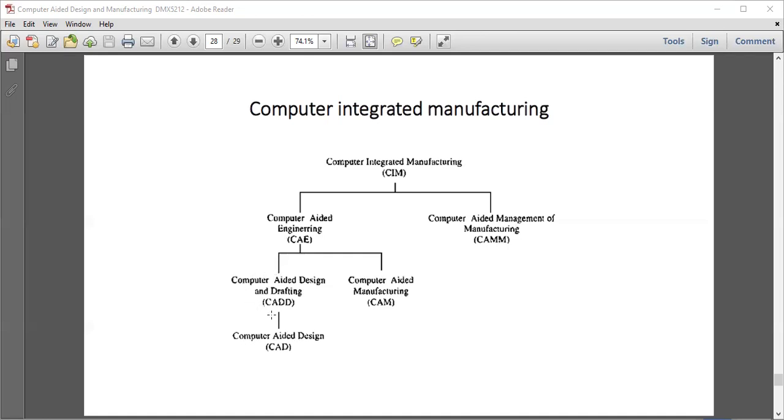If I say the usual sequence in computer drafting software, you already know this. You start by setting up: in settings, you set up dimensional units, what units you are going to use, what lines you're going to take, what paper size, and what scale you're going to use. Likewise, you do the setup, same as in technical drawing or engineering drawing. You make a cage and you name the scale, whatever parameters you use. Like that you are doing in settings, creating the background setups.